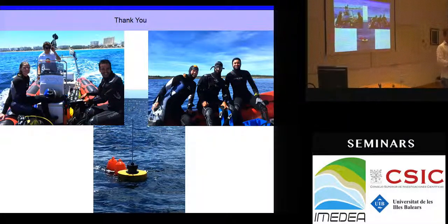If you're interested in beach erosion during extreme conditions, then I would say take XBeach, because it's designed for that kind of thing. If you want to study bar movement, I would use neither. But there's another model called Unibest-TC, which is specifically developed to predict long-term bar evolution, and that's at least a model that I know of that really works. But that's a 1D model, so it takes a transect and it can predict the bar evolution.